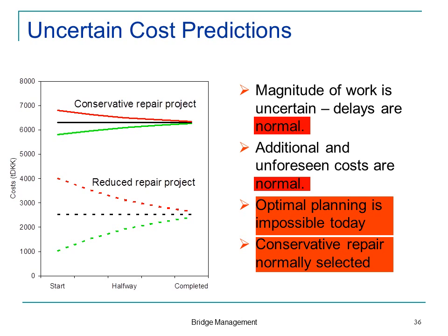Totally difficult to control. So what we normally do is we make a much more conservative repair project. We would, for instance, say, remove all the pavement, remove the top 8 centimeters of all the concrete, good or bad, remove the whole thing, cast 8 new centimeters of concrete and put a new pavement on top of it.